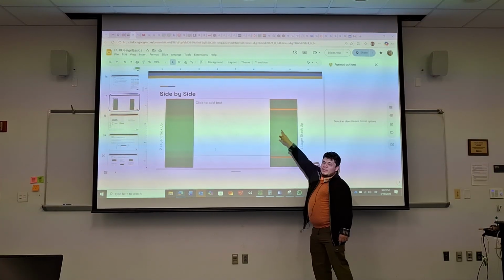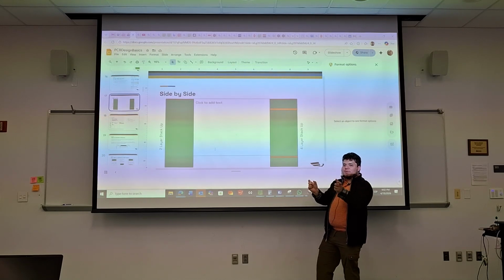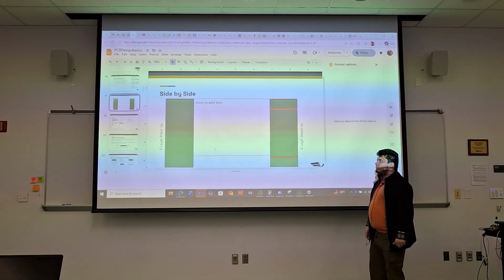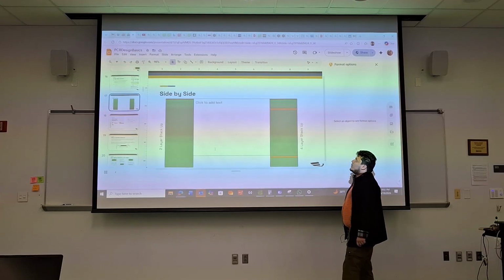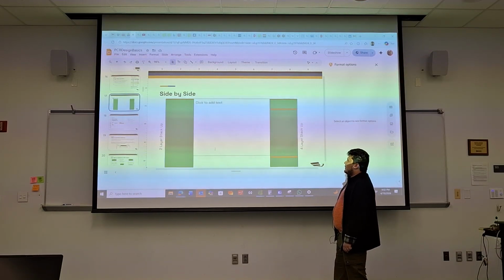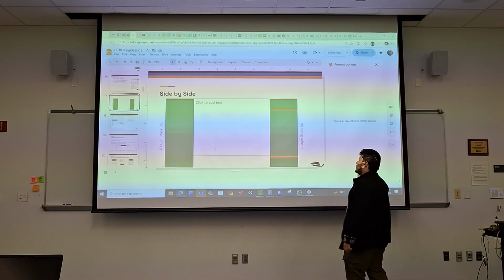That's a massive loop across the 62 mils of the board thickness. So if this ever goes to another rev, I would consider increasing the layers since there's a lot going on.